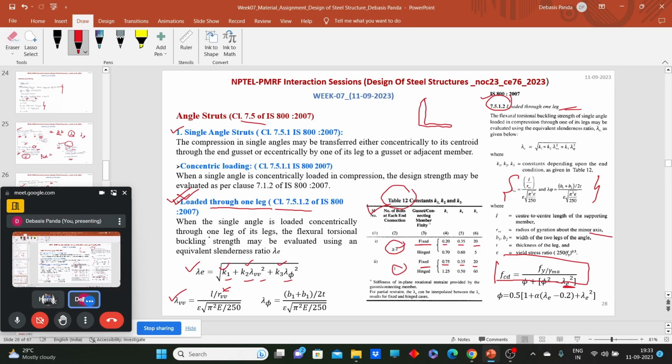Okay. Now, what is that sigma here? That sigma is the value of (250 divided by Fy) to the power half. That means we call it the yield strength ratio. Sigma means yield strength ratio. And pi square E, we know those values.